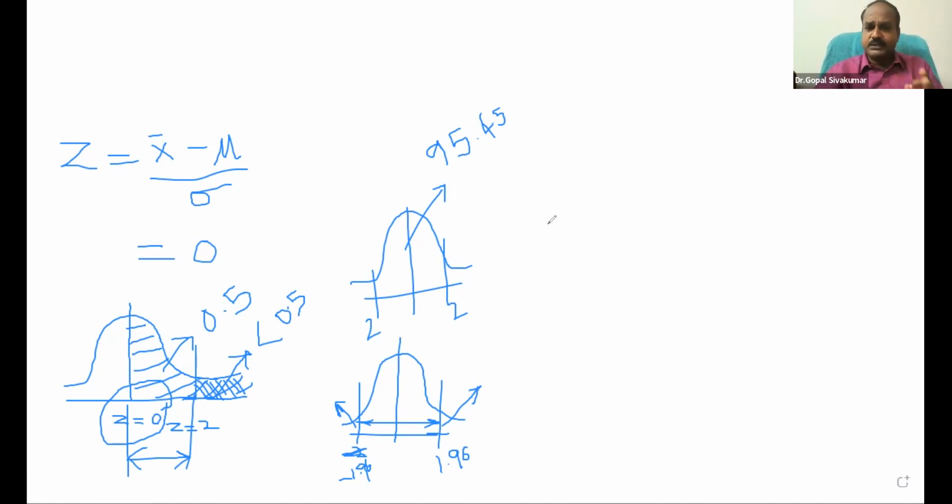So now my point is, as the Z-score increases, the deterioration also increases. Generally, statistically, deterioration up to 95% is considered normal. But beyond 95%, you only have the balance 5%. Any event that is observed beyond 1.96 is considered critical or significant. It can be anything. Please understand, it can be anything. It is not only applicable to thickness.